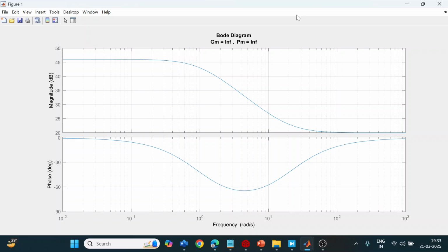So for this type of system, to talk about the stability, you need to add a compensator. Why the requirement of a compensator? A compensator is needed for system stability, or for improving something like settling time. Let's imagine that your settling time is initially 5 seconds without a compensator, and you want to reduce the settling time to 2 seconds. By adding a compensator, which one do you use: a lag compensator or a lead compensator? Those are the things you need to analyze.